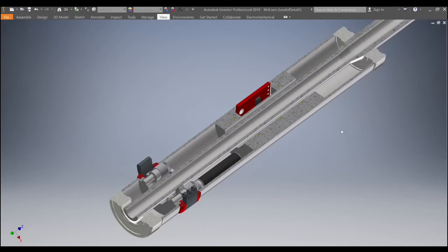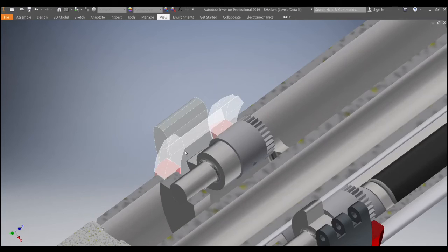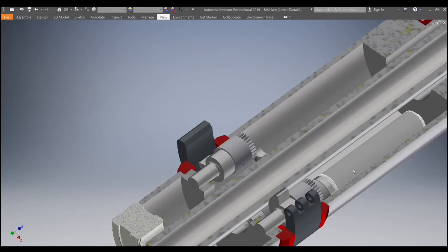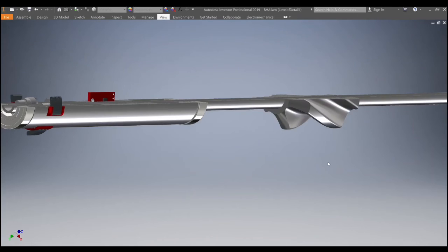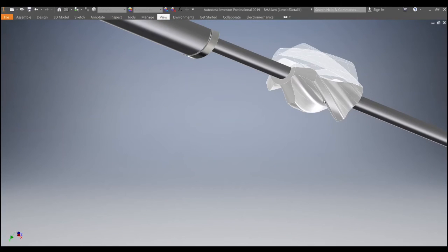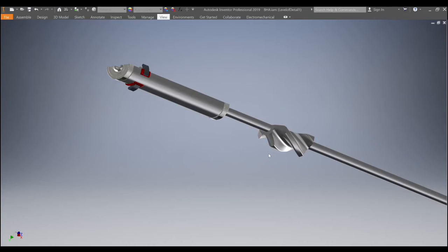The 4-pad system will push against the wall to provide the required side force to steer the bit. The pads are connected to the snail cam. It will be operated by a stepper motor for motion. The 2.5-inch long stabilizer will act as a fulcrum point. When the pads open against the wall, it will provide a side force that acts on the stabilizer and on the drilling bit to drill directionally.